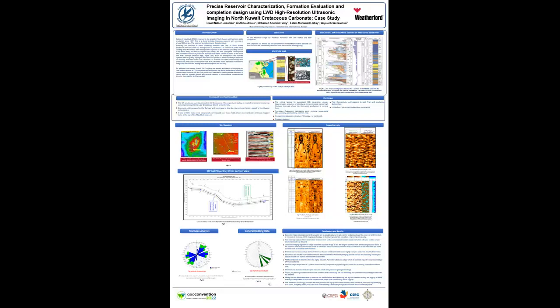So in order to improve the sweep and also to sustain the production, we are using many new technologies in this field. One of the technologies that we are using now is produce high and inject low to sustain the oil production. The arrangement is to facilitate injector water to gravity segregate with effective upward oil sweep, resulting in improved oil recovery and reducing the water cuts in the long run.